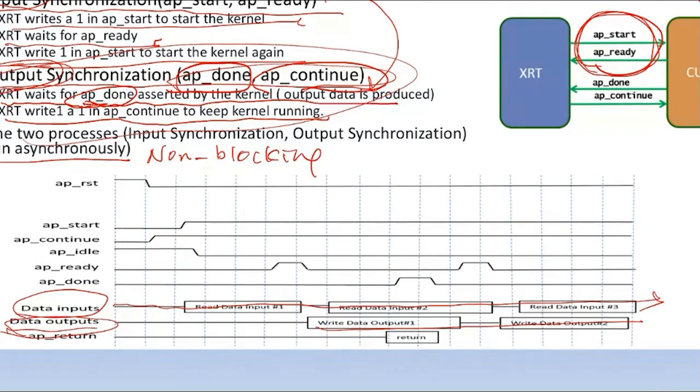Remember, in the system there are certain resources, for example the PCIe bus. How do you design a system and say my design is optimum? How do you evaluate this statement? I will look at whether the PCIe bus is fully utilized. If the PCIe bus is not 100% utilized, then maybe the computation resource is not enough to feed the data.